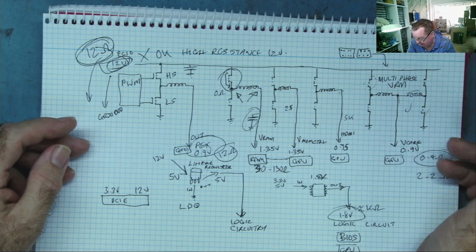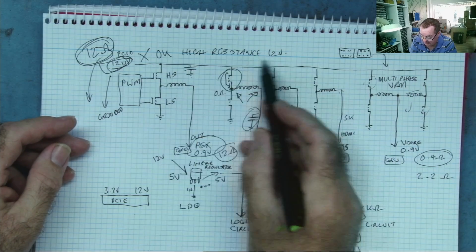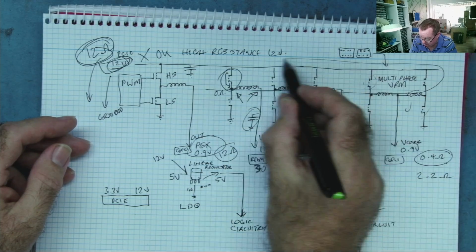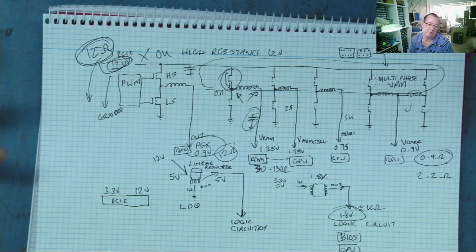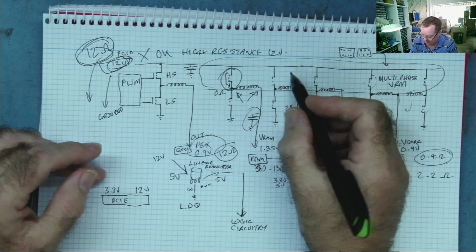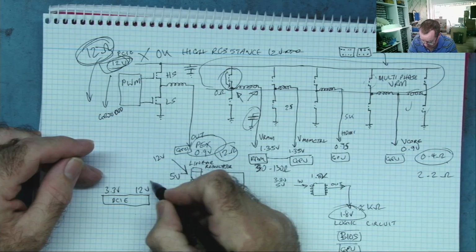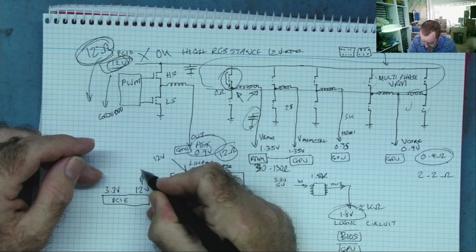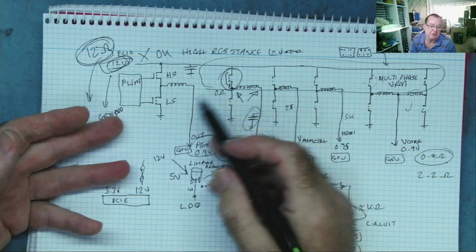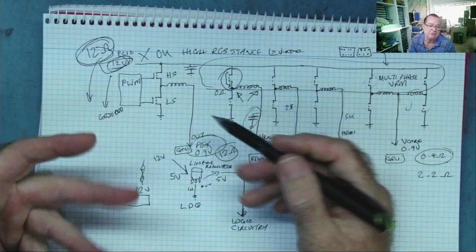Okay, if you find that, then because you have this high resistance on the 12 volts, you can say basically all these high side MOSFETs are okay, or they've got open circuit, or the fuse has got open circuit in there as well. Bear in mind there'll be a fuse in this circuit here somewhere coming in, and also from here there may well be a fuse. But assuming the fuses are okay, you can measure the 12 volts back to the PCIe, you can measure 12 volts back to these connectors.